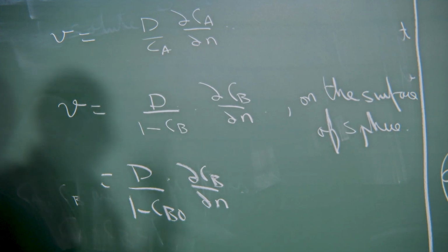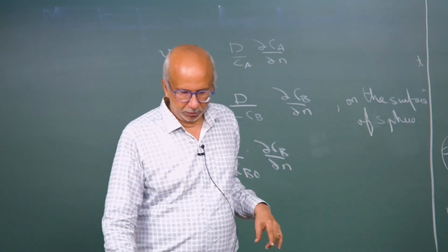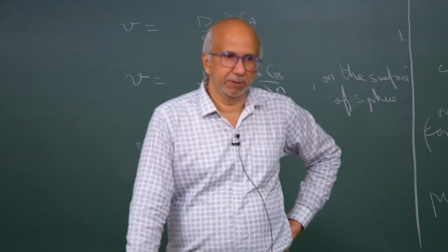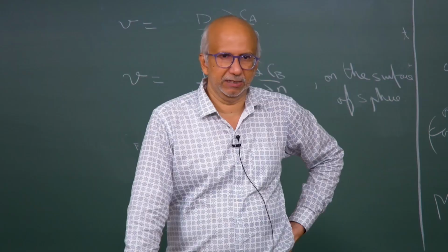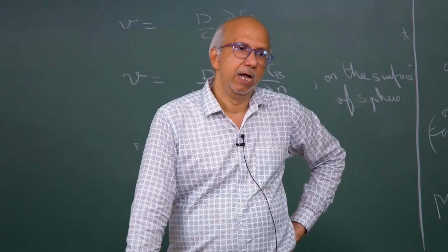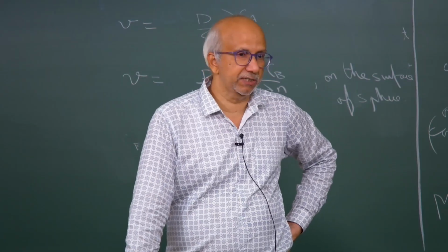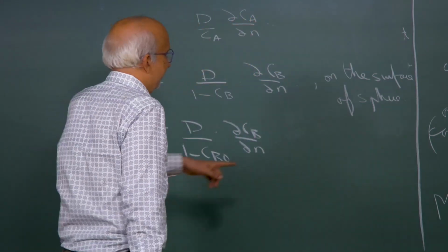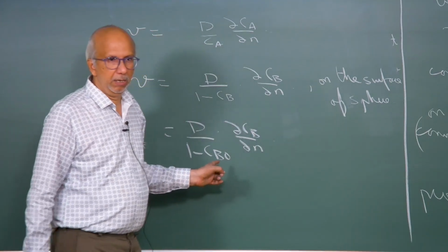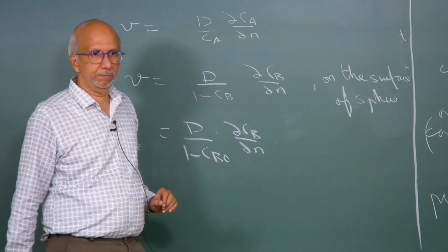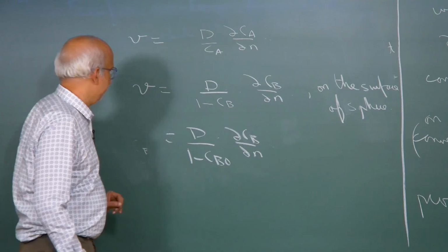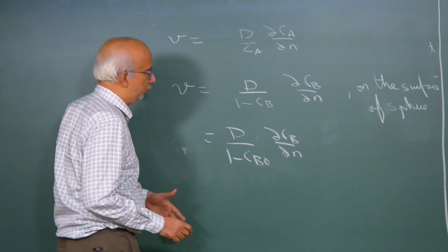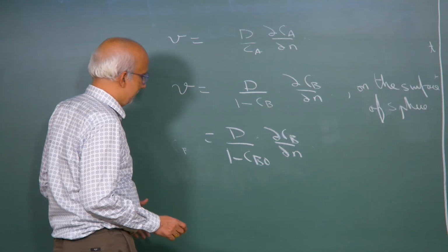So when you are trying to find the flux, the numerator in the Sherwood number, because Nusselt number is for heat transfer and Sherwood number is for mass transfer, you will have to consider both the flux due to convection and the flux due to diffusion. This is something I wanted to explain to you. I am not going to go through this in more detail.